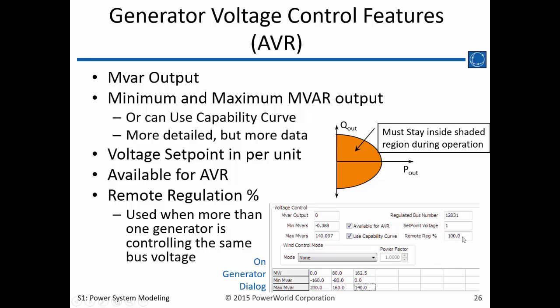So if you give 3 generators 100% each, simulator internally figures out that what they're really doing is 100 over 300, so they're each providing a third. The other option you could do is set each generator to be 33.333, and that's the same thing. Simulator will take 33.333 divided by 100 and determine that they're each supplying 1/3.